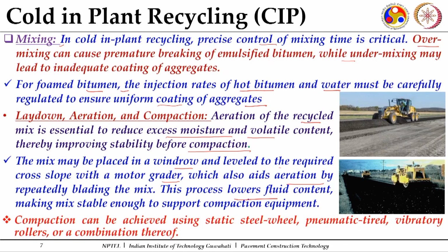This process helps to reduce the fluid content, making the mix stable enough to support the compaction equipment, and then your standard compaction equipment, which are vibratory rollers or specifically the sheep foot or pad foot rollers, are used for compaction of these stabilized courses.